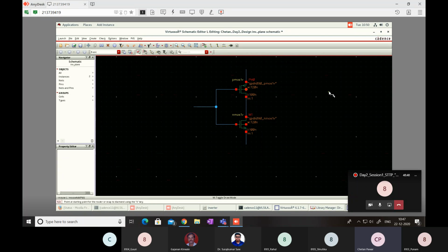Okay, Rahul, if you want to keep a wire floating, you just need to click there 2 times. Similarly, on the output side, you can create a wire. So one click, and here for this floating terminal, 2 clicks. Okay. So this way, I have created this inverter design. Now for this, I need to connect the input and output ports.